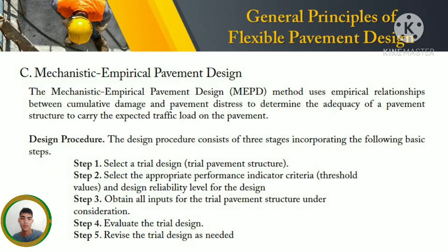Another general principle is the mechanistic empirical pavement design. The mechanistic empirical pavement design, or MEPD, method uses empirical relationships between cumulative damage and pavement distress to determine the adequacy of the pavement structure to carry the expected traffic load on the pavement. The design procedure consists of 3 stages incorporating the following basic steps. Step 1, select a trial design.